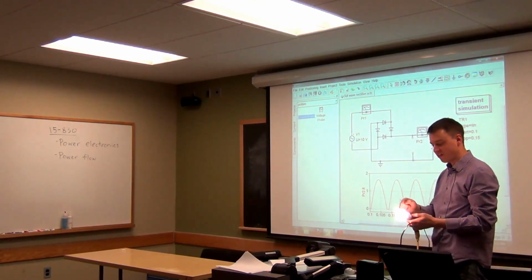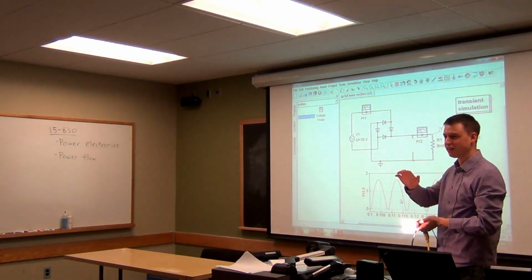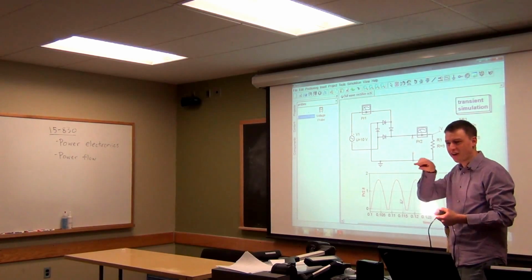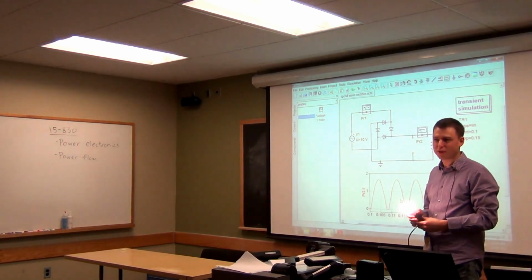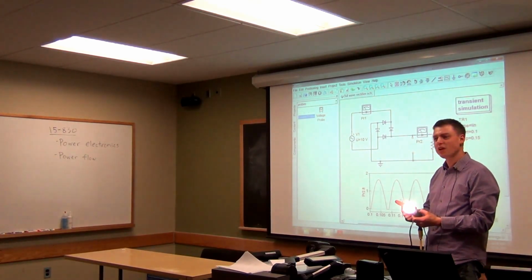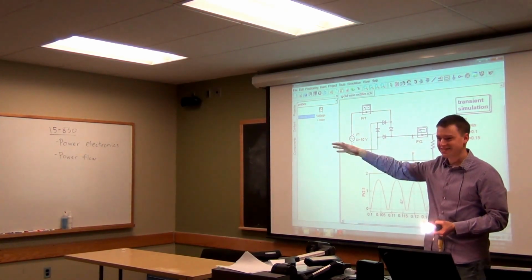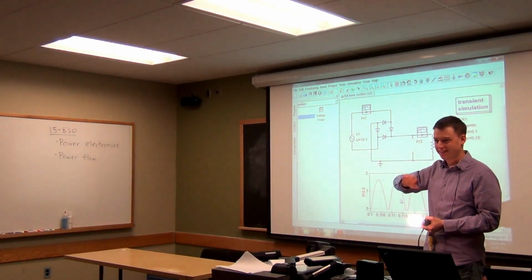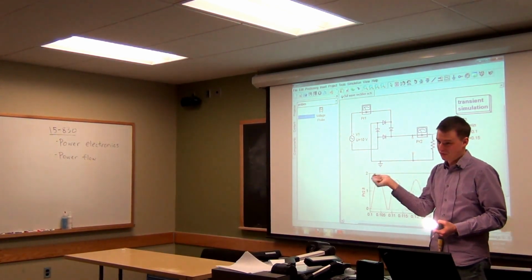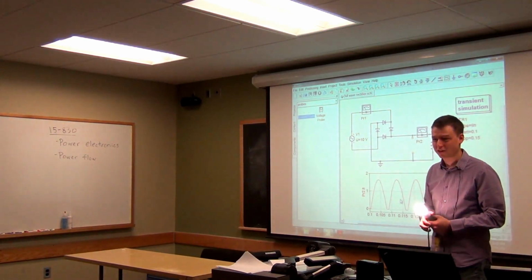And the reason why is that this has an internal system that actually will get a constant amount of power flowing through that LED, or approximately constant, so it'll always be on. Versus the Christmas lights, they just put AC sources right through a diode. And when the power's going the other way, it won't pass through, so they'll flicker. And they'll turn on and off.